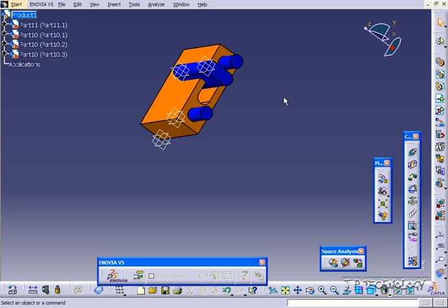With the positional assembly using the snap feature, it's just going to snap it into place, and as you see on the side, there isn't any constraints or anything showing you that there's still a constraint to say that this axis has to be touching that axis. So it's just going to move around. After you move it once, there's no history really behind it, so it doesn't have any driving characteristics.